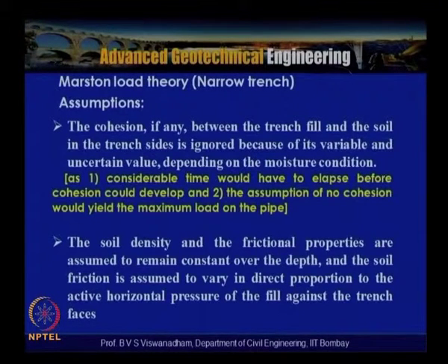So now we are going to understand Marston load theory for narrow trenches, and let us look into the assumptions which are put forward. Here the cohesion, if any, between the trench fill and the soil in the trench sides is ignored, because of its variable and uncertain value depending upon the moisture condition.